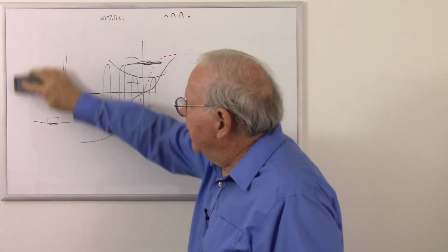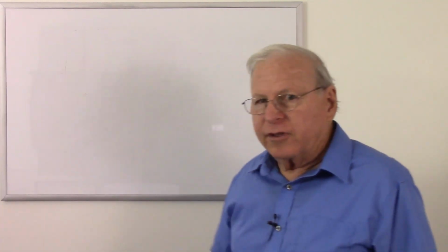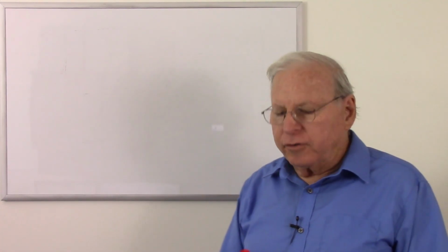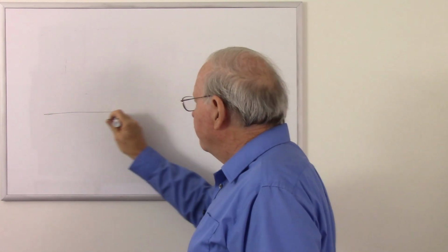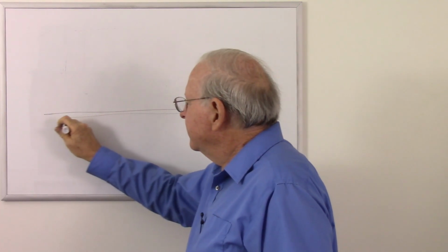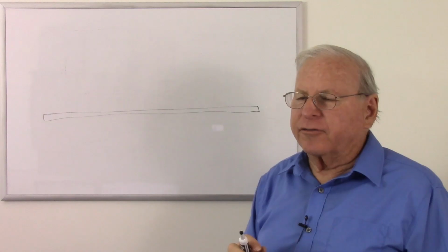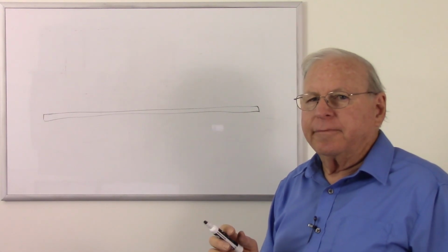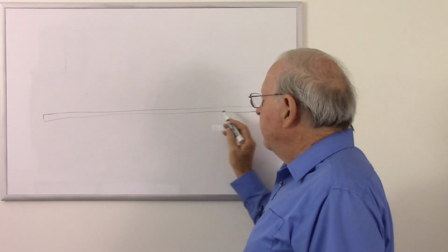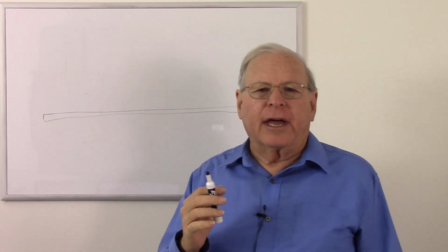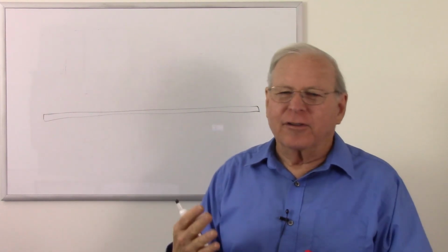So the wire recording, we basically had a steel wire. Different alloys may have given us different qualities that we could control, but now we've moved on to tape. So what is tape? Modern audio tape is going to be a base, I'll just draw it as a chunk here, of, I don't know if I'm using any other material other than polyester. Maybe in the early days they used something different, maybe acetate, maybe film stock, who knows what. But modern tape is made with polyester. You may know that as mylar. So DuPont calls polyester sheet mylar. Everybody else calls it polyester.